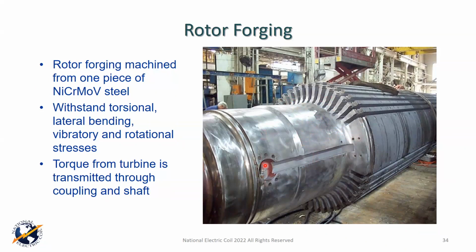We've got a radial stud right here. This is a channel for what's called a J-strap. So the electrical energy is coming up through that radial stud to the J-strap. The J-strap comes around and hooks around and would connect either to the bottom or the top of the number one coil. Most common is to connect to the bottom, but there are some interesting designs that do connect to the top. These are all the slots for the coils on each side.